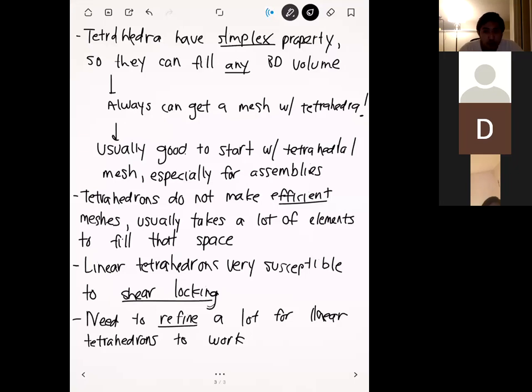And so in my own work, I've used mainly just linear tetrahedron, because mathematically it's the simplest to deal with, and you can fix most problems by refining, and that's usually an easier route to go than trying to implement quadratic tetrahedron. Right? But that's a problem that's really unique to just writing your own code for these things. Okay, so any questions on this so far?